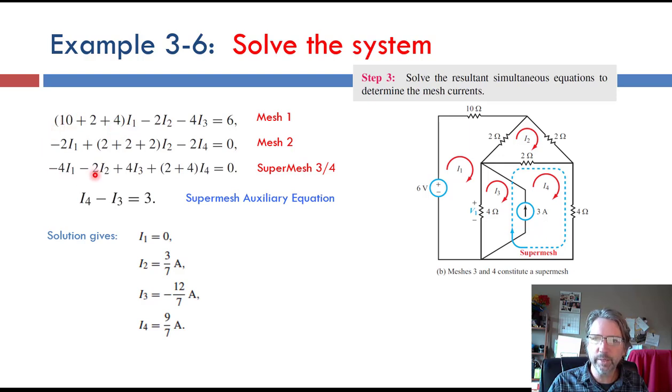So if you're writing these equations and you add in something with amps as its units, that's going to be a mistake. So the units have to be consistent through an equation. Kirchhoff's voltage law is in volts. Kirchhoff's current law, back in node analysis, has units of amps. This is in volts because it's Kirchhoff's voltage law. This one is talking about current sources, so its units are amps.